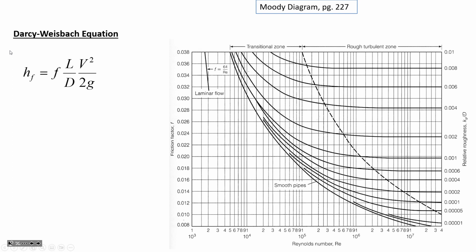So in the energy equation, the trickiest thing often for us is estimating the effect of pipe friction. And what makes it tricky is that even for the same kind of pipe, if the water is moving slowly, there will be a completely different friction effect that applies compared to if the water is moving quickly through the same conduit. So that difficulty in estimating the friction factor largely falls into the challenge with calculating F, the friction factor in the Darcy-Weisbach equation.